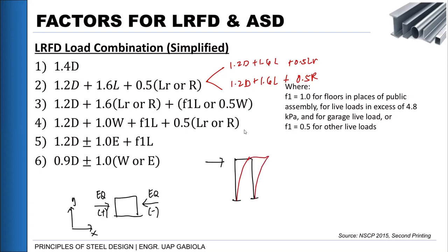Okay? The lateral load tends to overturn our structure, but it does not overturn completely, because there are also resisting or righting moments existing in our building. So the code assumes that not all of the weight of our building helps to overturn it. Some of it helps our structure retain or go back to its stable condition. So it says we allot 10% for that effect. That is what number 6 is stating. Whenever a lateral load happens, it considers that only 90% of the dead load is usable when the structure overturns or deflects. So this is our load combo for LRFD. Okay?